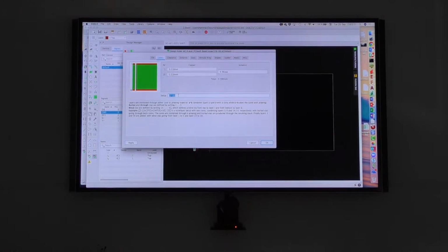I have these brackets, I think it is, where you say I drill from layer 1 to layer 2, so I don't drill through the whole stack, but I do it to a certain depth. Then I have to define something like this. I can go on and say, okay, I want to have a 4-layer board. Let's do it this way too, and then I need this, and then I say plus 15, plus 16, so I have 4 layers.